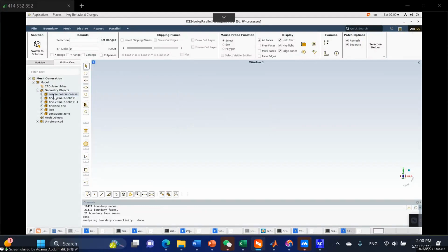So you are not going to generate this mesh yourself, okay? You are going to input numbers, values on various parts of the train that you have already grouped and named. Okay, so I want this mesh size to be equal to 1 millimeter. I want this mesh size to be equal to 0.5 millimeter. So faceting helps you to put these values first and then save it. Then you will need to import the surface mesh using these saved size fields that you have created from the faceting option. I don't know if you understand.